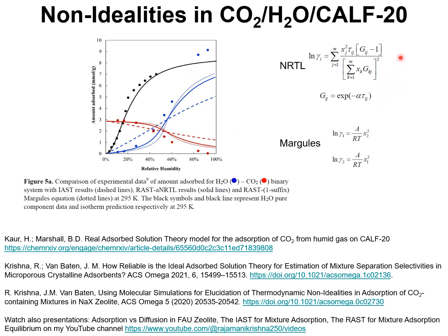And I would venture to say that the correction factor that I introduced a few slides ago, and which I describe in detail in several of my own publications, the correction factor 1 minus exponential of minus C times phi, where phi is the surface potential, must be introduced in order to have the proper limiting behavior, as phi, the surface potential, tends to small values.